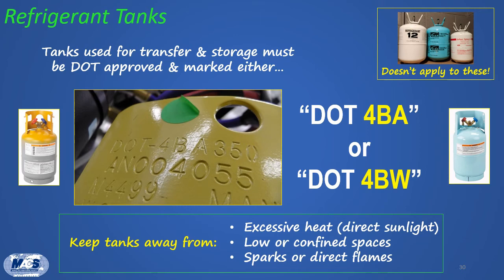And remember, when you're working with these tanks, make sure you keep them away from excessive heat. So that means direct sunlight. Don't leave them out in the sun in front of the shop. Make sure that you don't store them in low or confined spaces. And of course, keep them away from sparks or direct flames.